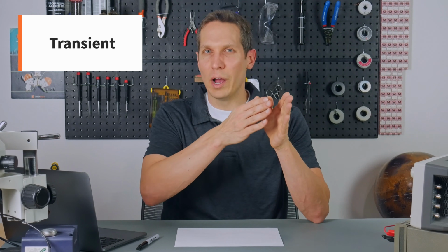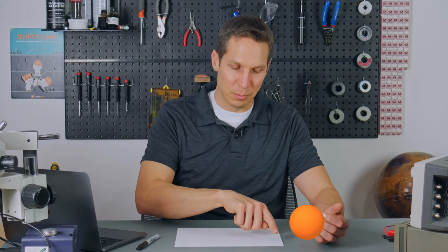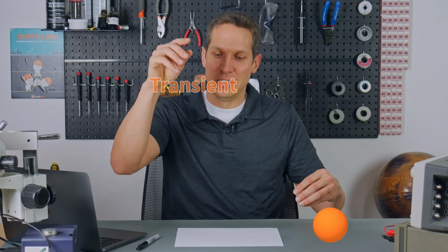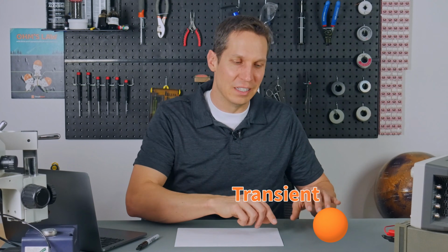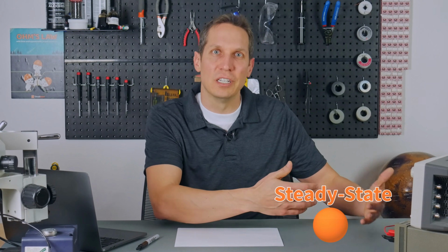And then the other thing is the transient, which is basically what happens between putting in the input and getting that steady state output. So let's use a bouncing ball, for example. If you take a ball right here and then you drop it, let's say at time equals 0, the transient is it falls, bounces a couple of times, and then it stops. So in that system, at time equals 0, with the input of me dropping the ball, the transient response is the bouncing of the ball, and then the steady state response is where the ball ends up and stays until a further input is given to it.